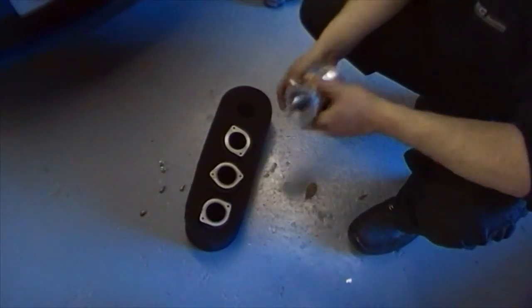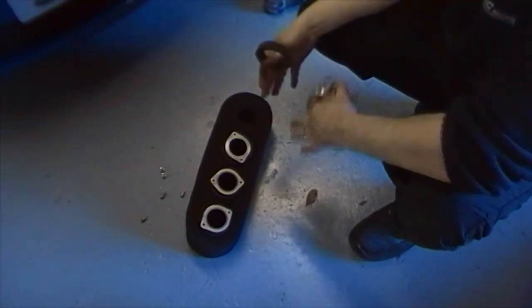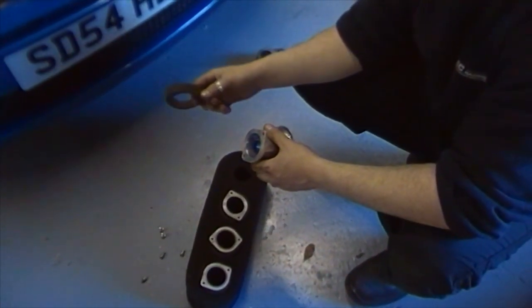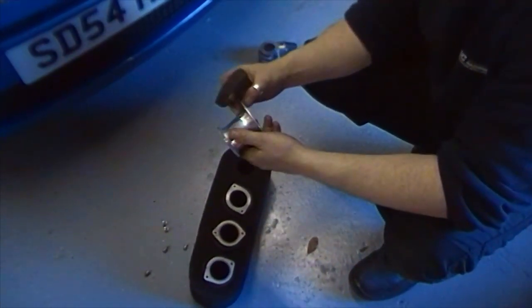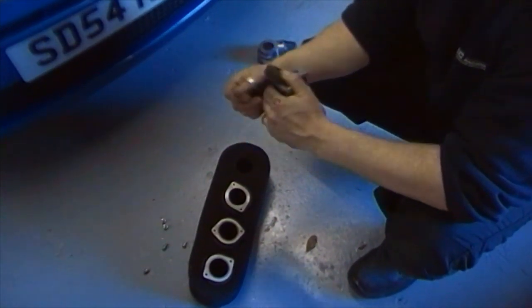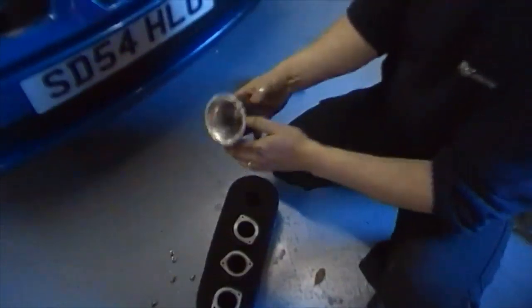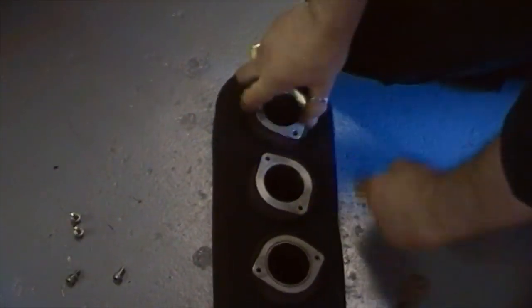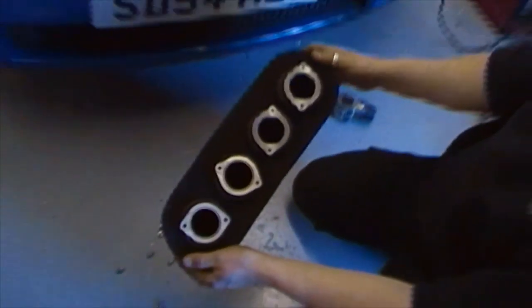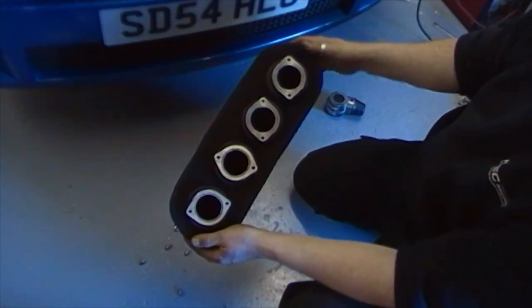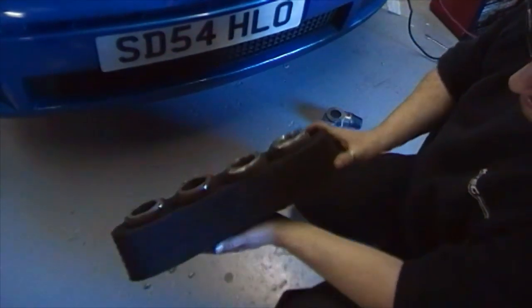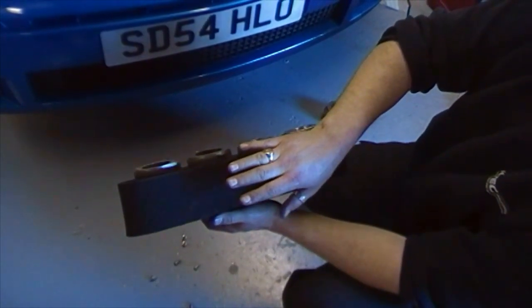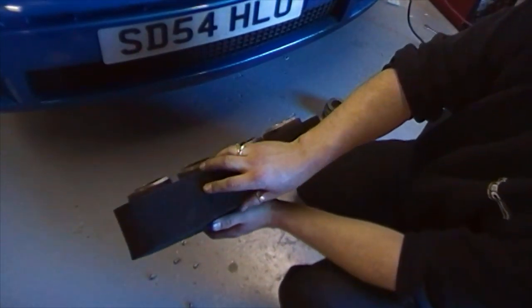We have the air filter assembly, and we can see how the assembly goes together, and it's very important to use the spacer rings to keep the air filter off the end of the trumpet. So we'll install these here, and then the trumpet needs to go inside the air sock first before we can install it on the engine. You can see here the orientation of how it all goes together. At this point it's also important to realise that the air filter is actually a wedge shape, and it's thinner at the top than it is at the bottom.